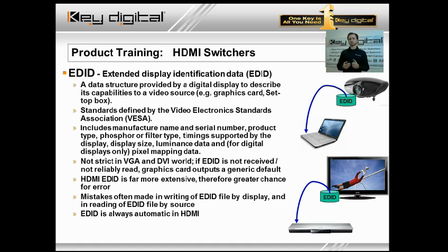If you take a look at that VGA pinout, that's on the DDC channel, as it's called, where that data was given from the display to the source. In the VGA world, if the computer didn't receive an EDID file, it would typically just default and output something rather generic.